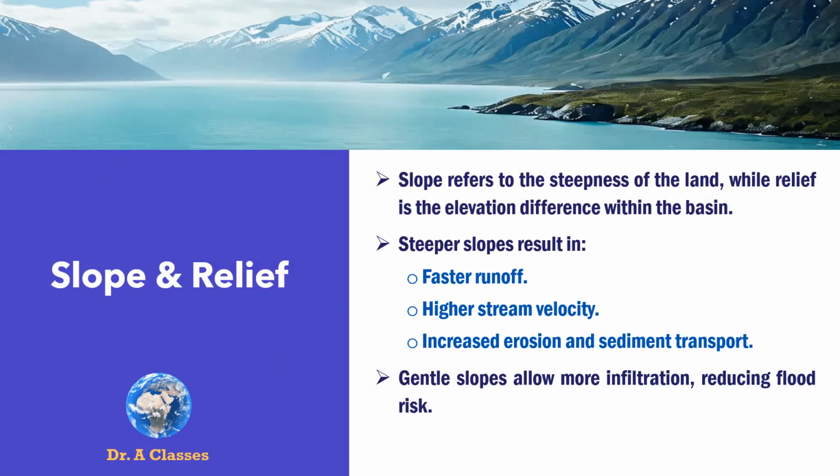Slope and relief. Slope refers to the steepness of the land, while relief is the elevation difference within the basin. Steeper slopes result in faster runoff, higher stream velocity, increased erosion and sediment transport, whereas gentle slopes allow more infiltration, reducing flood risk.